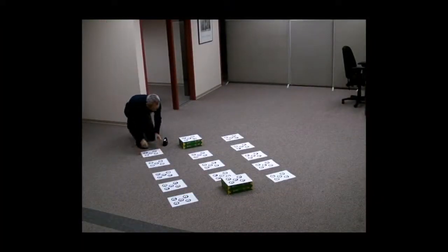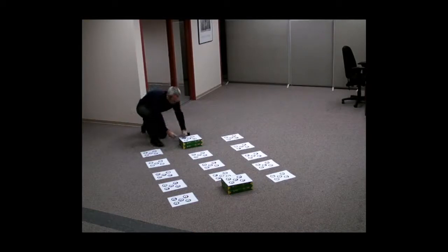Lay the sheets out to form a calibration area. You can optionally raise or lower some of the targets. This added depth to the calibration area can be especially useful with longer focal lengths. Make sure your sheets are fixed down so they will not move between photos. Even a small breeze caused by walking can affect the target positions and result in a poor calibration.